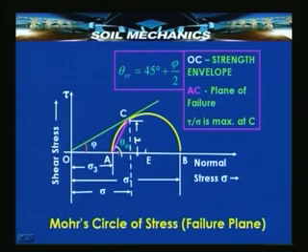So, the plane AC, which has been plotted from the pole up to the point C, is nothing but the plane on which act the stresses tau and sigma corresponding to failure. So, AC becomes the failure plane. This failure plane AC makes an angle with the horizontal, which we now call theta critical, because that corresponds to the critical possible angle.